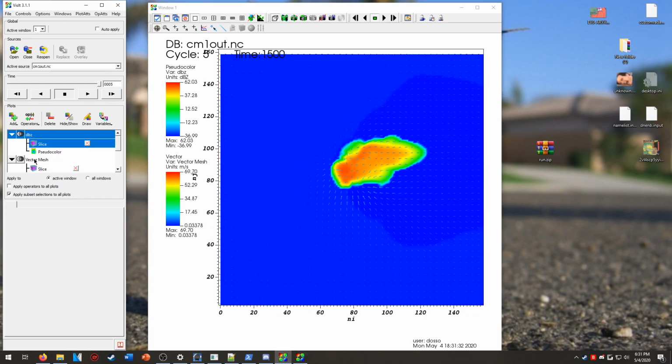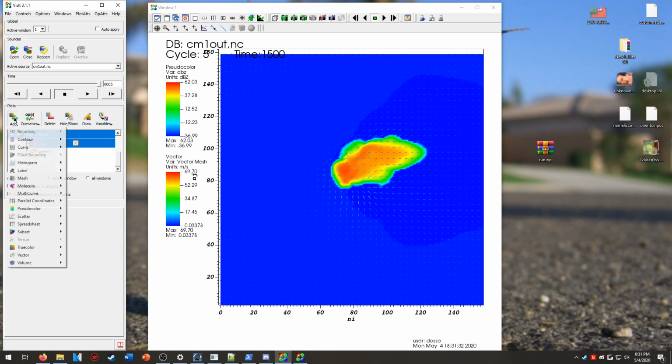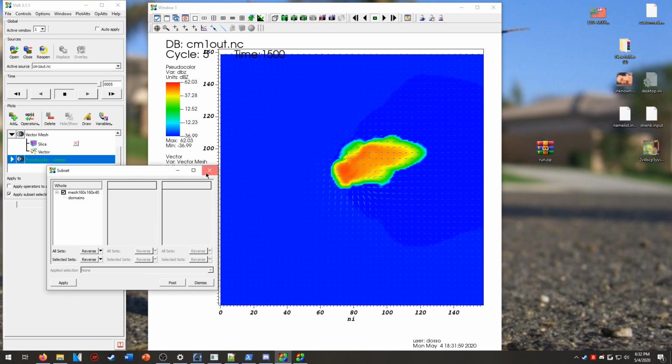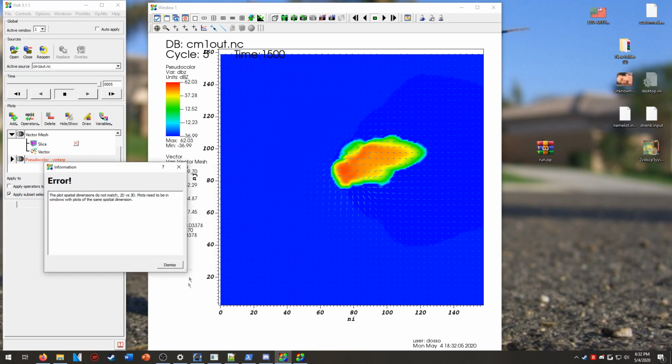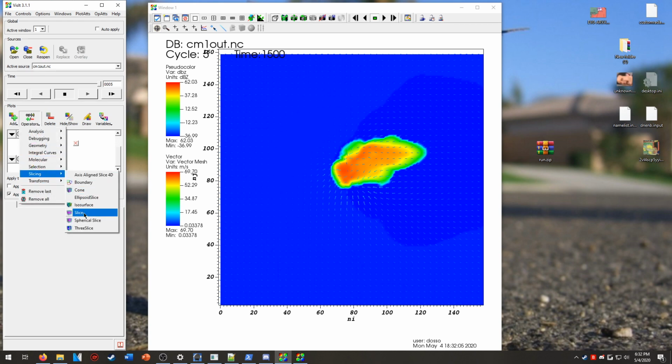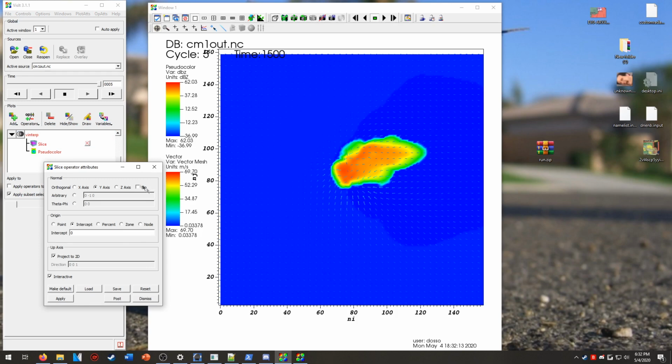One of the other things you can do is add base velocity. So we'll go to pseudo color again, and in this instance we're going to do vertical velocity, so winds that are blowing up and down. If you color this right now, let's see, that's because I didn't add it as a slice. That's one of the things that'll get you. So we had slice, surface, change it to Z-axis, apply, boom.